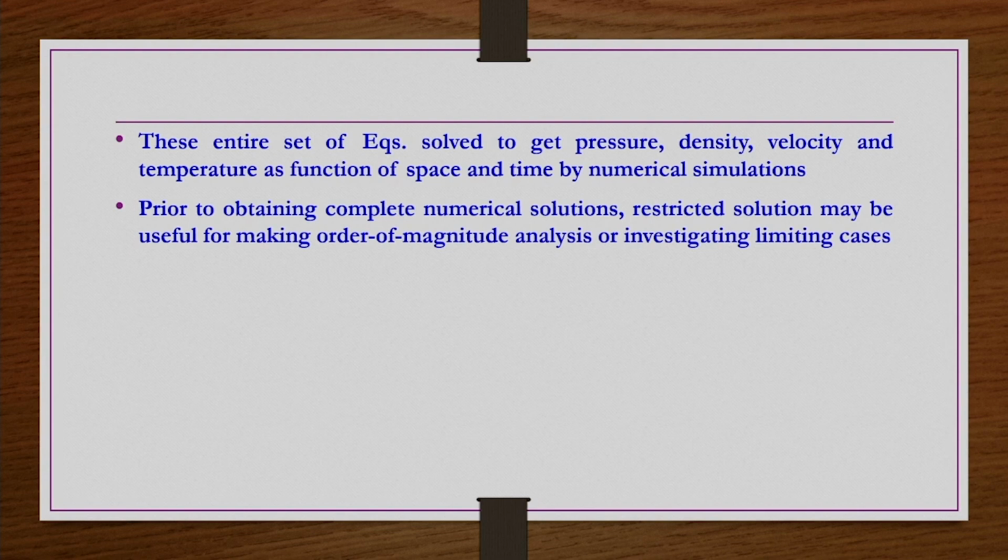Likewise, in non-isothermal flows of any system, if you make some constraints, you are going to have certain advantages, like making an order of magnitude analysis and investigating limiting cases. For example, getting back to viscoelastic behavior, when a viscoelastic fluid flows through a packed bed of particles of different sizes, we have seen that under one condition of particle size, the viscoelasticity is not necessary to consider. That is what is meant by order of magnitude analysis.